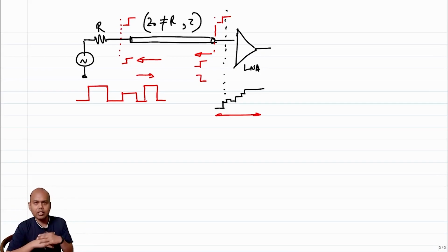Reflections are okay as long as there are no delays, but if there are reflections and there are delays, then you are going to see a very slow settling, and because of that you are going to get, in this context, intersymbol interference. Okay, so in the context of sinusoidal waveforms, when you have modulated sinusoidal waveforms, you can have similar issues.